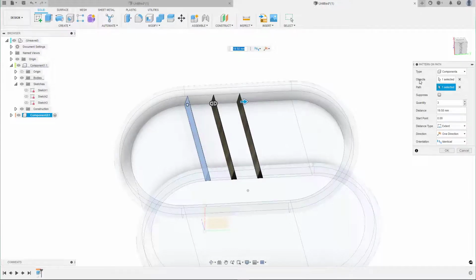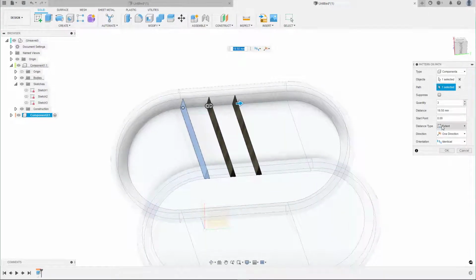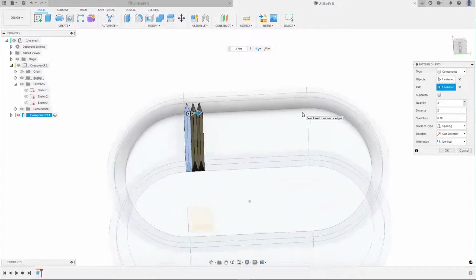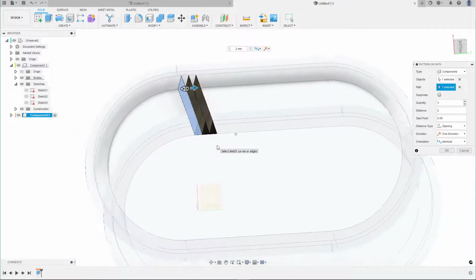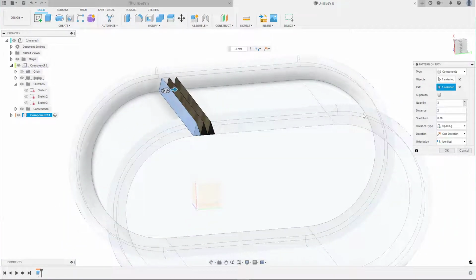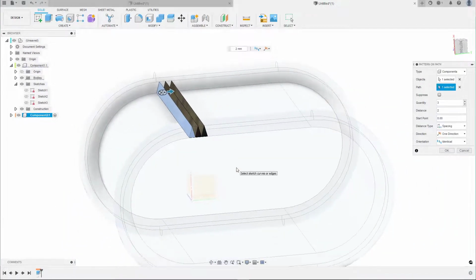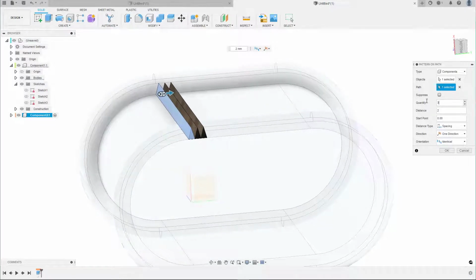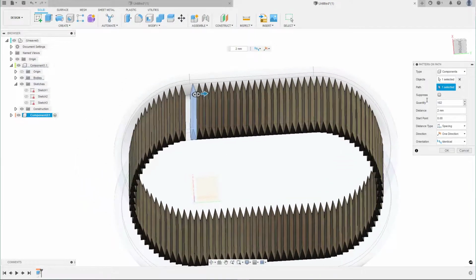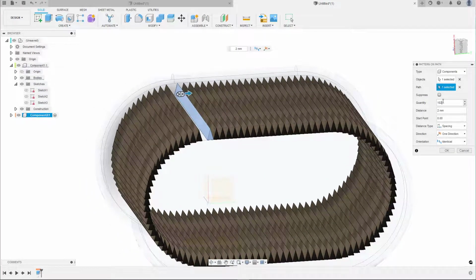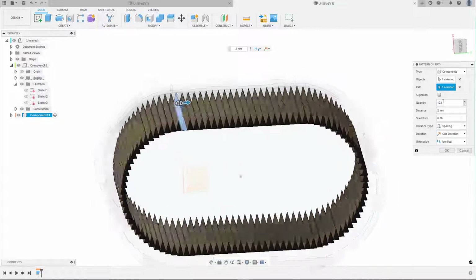First, we're going to use distance and not extend. So distance, the spacing, sorry, between every triangle. We know our base is 2 millimeters, so the spacing is going to be 2 mil. Right away I get all triangles stacked together. And because we calculated the full pad, that was 200 something, I know I'm going to use about 102 or 103. 102 is a missing one, so 103 is going to be better.